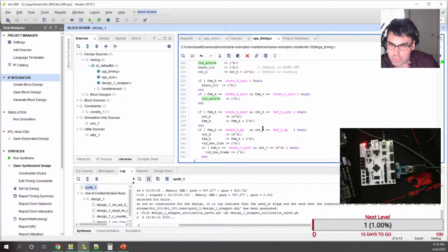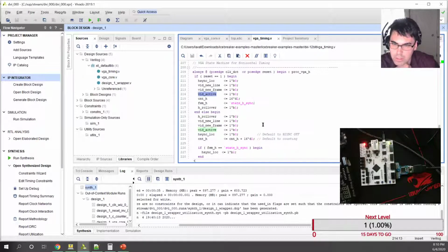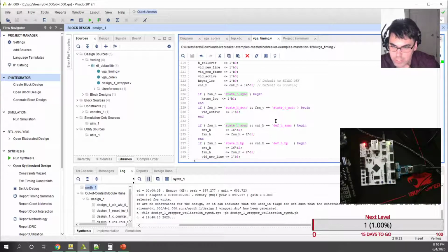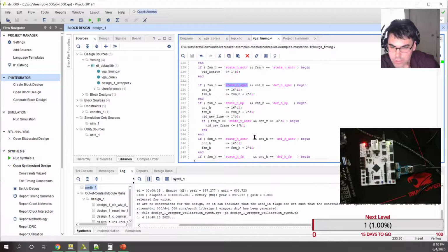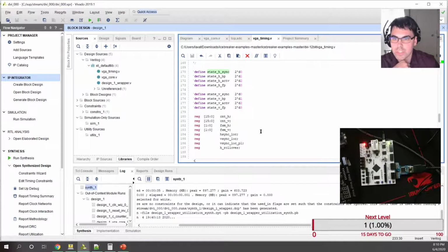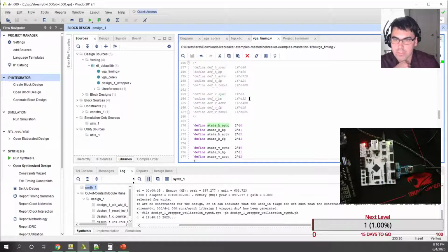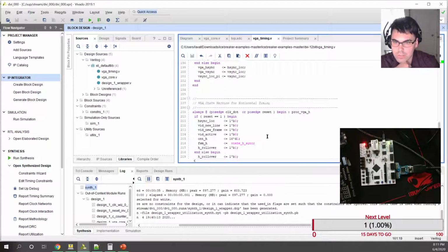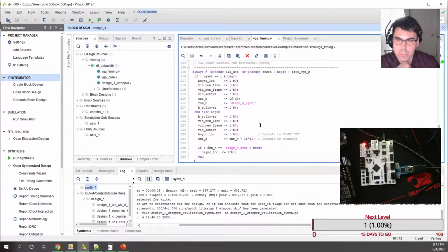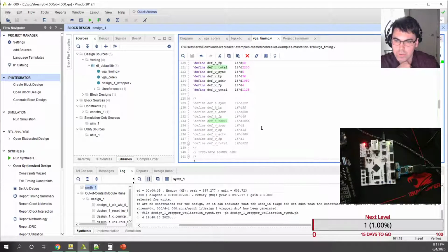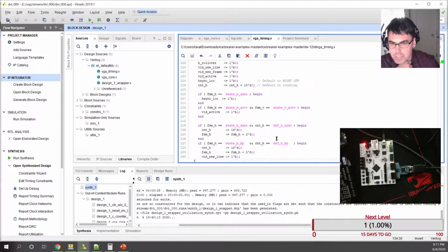Doesn't really matter per se, but what should we begin on? So it looks like they begin with the H sync. Let's make the state machine sync, back porch, active, front porch. That sounds good. Are the totals ever used? Totals are never used. So it's purely just counting these 4 different values. And active is high when this and this one are high. H sync is high when that one is high, and V sync is high when V sync is high. Yeah. So pretty basic.